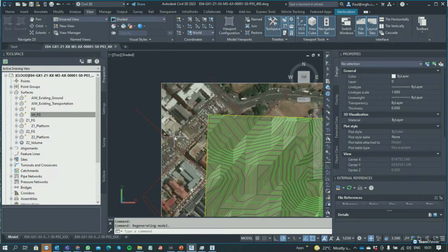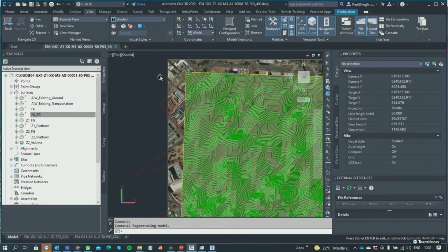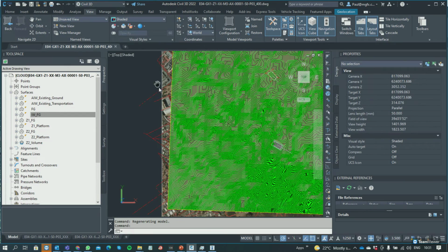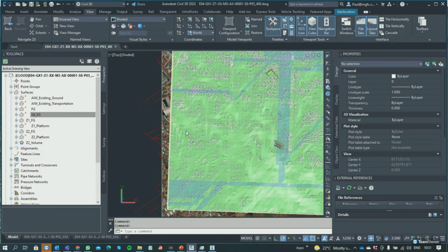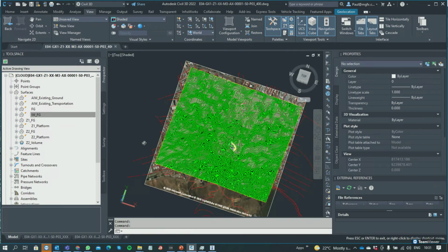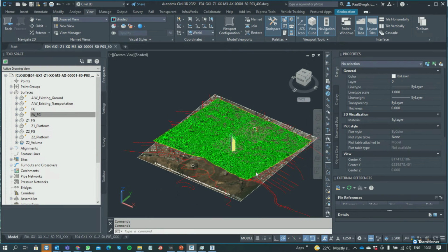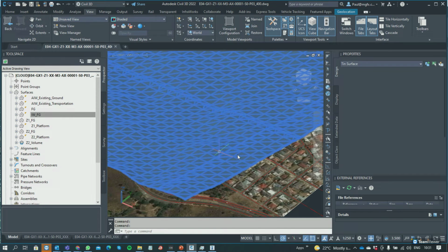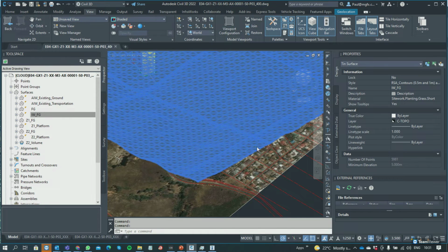It is generated within Civil 3D by virtue of the coordinate system that we've chosen. I've just cropped the imagery to underlay the Infraworks topography that I brought in. I was originally just interested in the topography, and there you can see, for example, what the topography from Infraworks would look like. Now, it's quite rough.